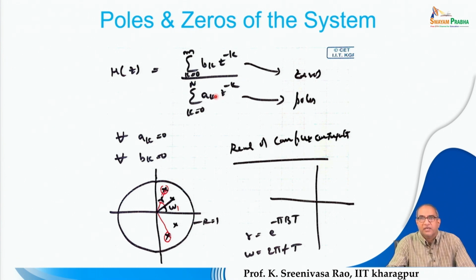But it is not accurate, because with an all-pole system we cannot model the anti-resonances or the zeros at all. We are assuming there are no zeros, but that is not true. That is the approximation we are making in the analysis of speech. Coming to the analysis of the pole-zero system, for example for the approximation, if the coefficients of the numerator polynomial, the b_k's, are 0, then it becomes an all-pole system.